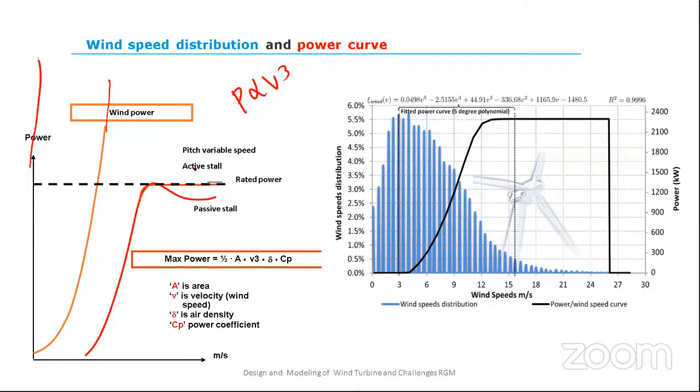Okay. So on that power curve, this is the stall controlled machine. This is the pitch controlled machine. I will explain the stall controlled machine also. There will not be any bearings between the hub and the blades, right? So this is the blade. Here I have the hub. There are no bearings between the hub and the blades, right? This is the stall control machine. Now I have to limit the power. The purpose of this mechanism is to limit the power.